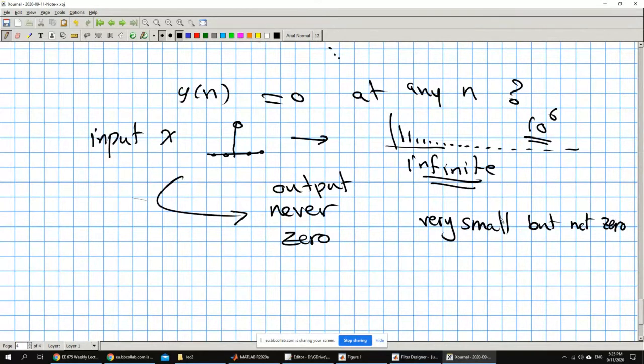So if you consider this filter compared to FIR, FIR looks much simpler. You know exactly when it's going to be 0. You don't have any problems with this. Imagine that you have a system that would produce an infinite number of response points. And you're not going to have only one impulse for a practical system, otherwise it would not be practical. Basically, I have to use it on signals. Imagine that you have an infinite response from one signal, and another infinite response from another. You have multiple inputs coming in all the time.